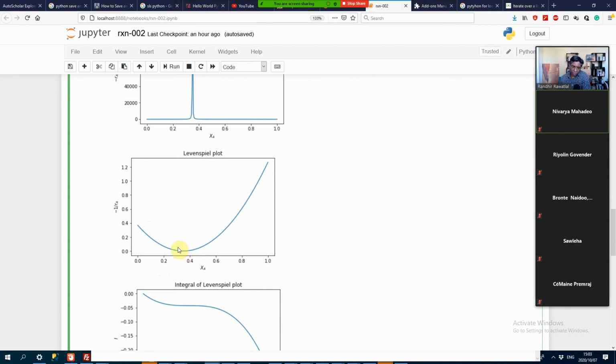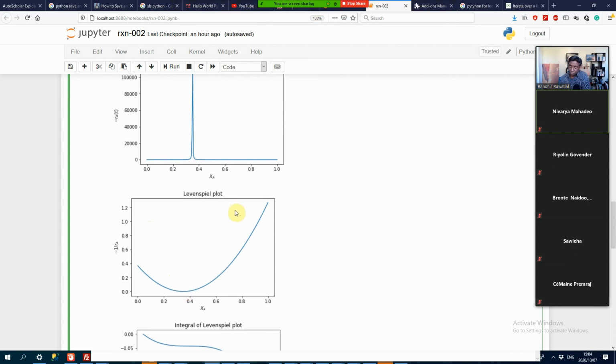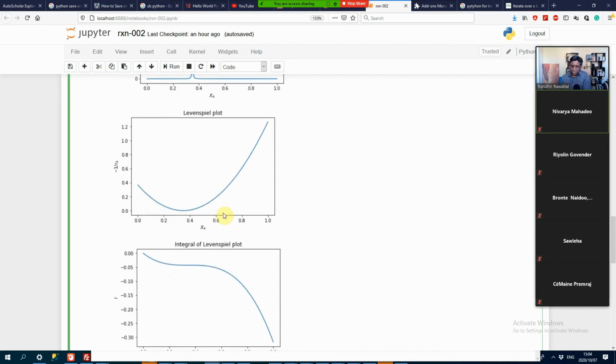You're having a high conversion under these weird kinetics. A high conversion actually means a better rate. So in your CSTR, we know the CSTR is always going to give us a low concentration. And if you have a low concentration in a region where a low concentration means a high reaction rate, then you've navigated the kinetics successfully, right? So once more, your CSTR always works at a lower concentration, and you've got kinetics in this case where a low concentration gives you a high reaction rate.